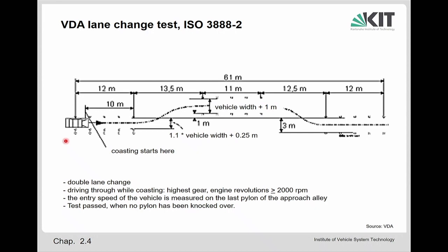And this is the situation where now the rollover takes place, because it cannot slide anymore. It has so high vertical forces that we have super high friction forces transmittable, and then the vehicle will not slide anymore. It will roll over. Okay, and that's a situation.